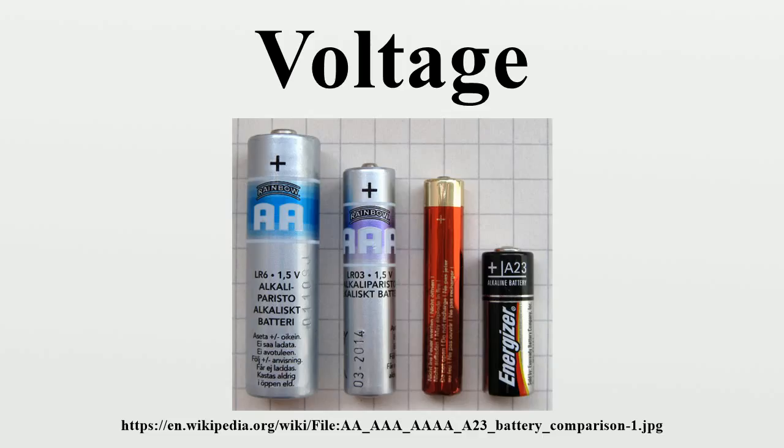The voltage between the two ends of a path is the total energy required to move a small electric charge along that path, divided by the magnitude of the charge. Mathematically, this is expressed as the line integral of the electric field and the time rate of change of magnetic field along that path. In the general case, both a static electric field and a dynamic electromagnetic field must be included in determining the voltage between 2 points.